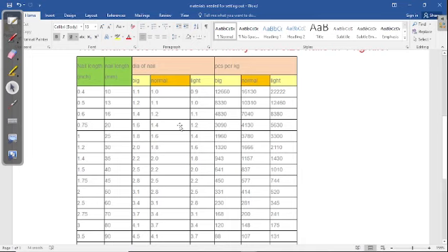Now, let's go to the columns that concern us. We are dealing with 3 inches nail and 2 inches nail. Firstly, a 2 inches nail has a length of 50 mm, and for the diameter, we have the big size of 2 inches nail, we have the normal size, and we have the light size.